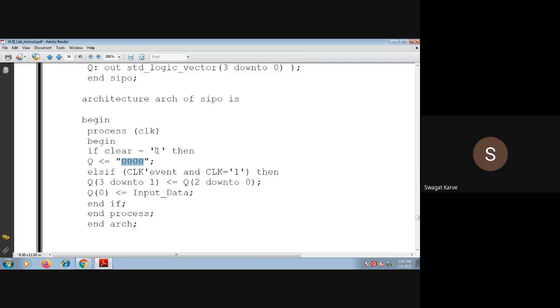We have cleared all the flip flops, and at the output side you will receive only all zeros, because it is parallel out. Output we are receiving parallelly, but each flip flop will receive input serially only. Step by step it will receive the input, but when the clock pulse is triggered, it has to produce the output simultaneously, that means parallelly.